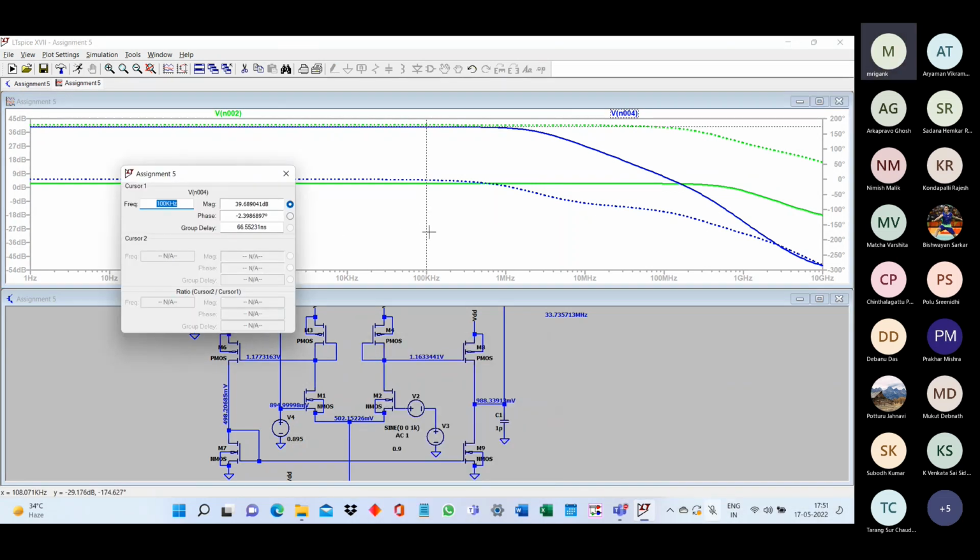So right now, let us see. The low frequency gain remains the same. At high frequency, you can see the 3 dB point has gone down. It is now almost below even 10 megahertz, just a few megahertz of 3 dB frequency. You can see it is around 3 megahertz. And now you can see the 0 dB point. The 0 dB point is coming at this, your 200 megahertz, and for 200 megahertz, what is the phase?